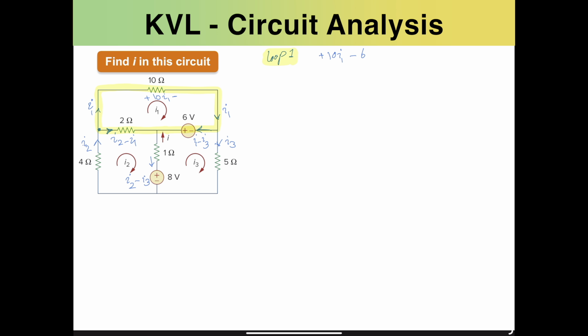If I2 minus I1 is a positive value, the voltage drop across that is going to be positive on the left and negative on the right. When we enter from the right side, we first see this negative terminal. That's why we need to multiply a negative sign to 2 ohms multiplied by I2 minus I1. So we would have minus 2 times I2 minus I1.